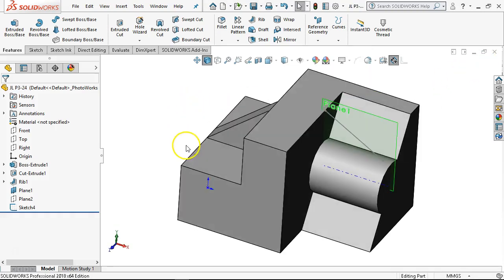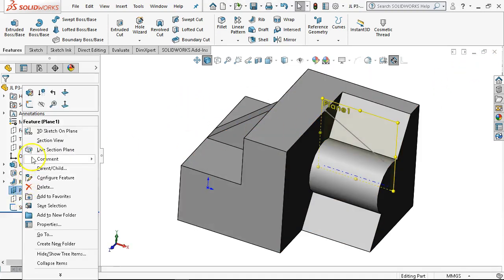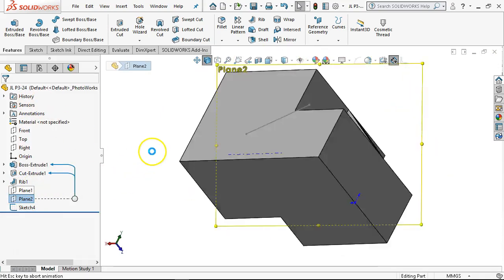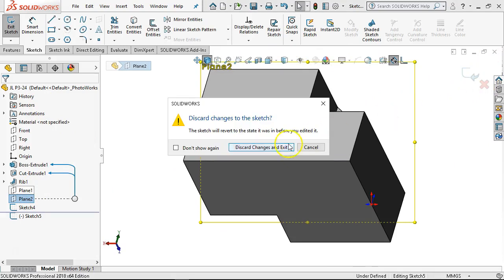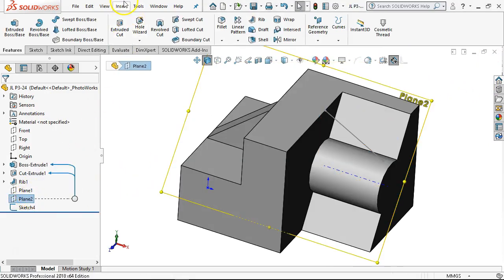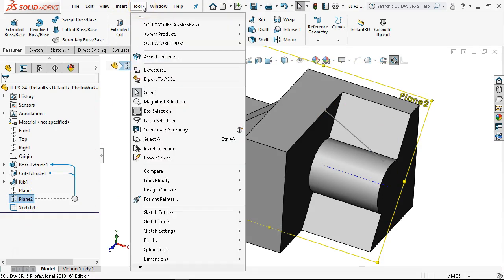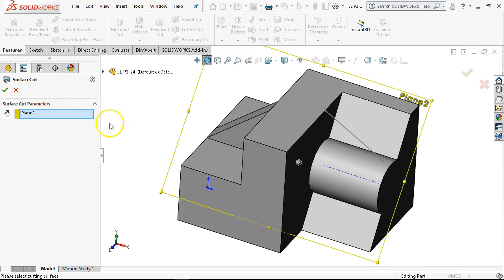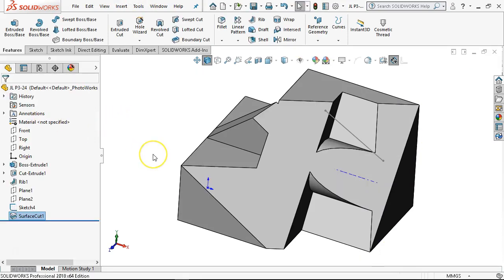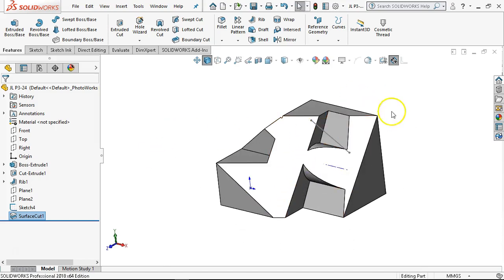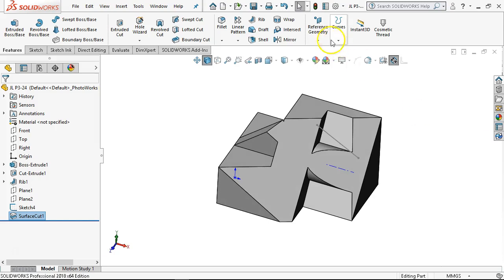All right, so when we're done with the planes, we will hide those. Oh, and then what I was going to do with plane 2, if that worked. Oh, nope, we didn't want to sketch on the compound. Sometimes the plane is handy for using it as a cutting tool. So if we insert a cut and cut with surface, plane 2, I can chop the compound with that surface or with that plane. I can also generate a surface if it had curvy or wavy whatever's to it.